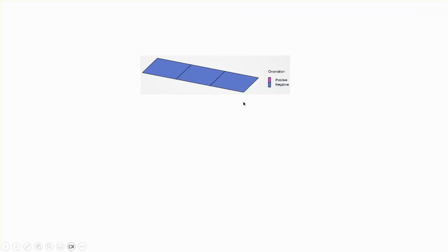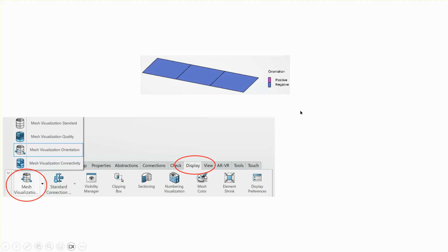So if you have a surface like that, and I'm going to do this example for you, it can be asked to be colored. And notice that this top view shows that the top is right there, and that is the negative side of the shell element. Whatever you're looking at is the negative side, or the bottom side, of the shell element. And if I wanted to change this, I can do it through the following sequence that I'm going to show you later on.